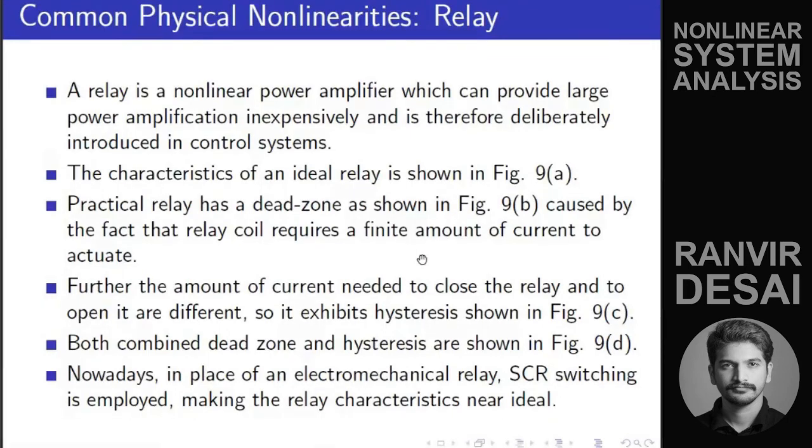It was the most used controller back in the day, but it is no longer. Nowadays PID is very commonplace, but still in cases like home automation, you just need on and off, right? So a relay can be used there. Nowadays in place of electromechanical relays, the ones that make the tuck tuck sound, SCR switching is employed. SCR, you may have studied in power electronics. So that is employed.